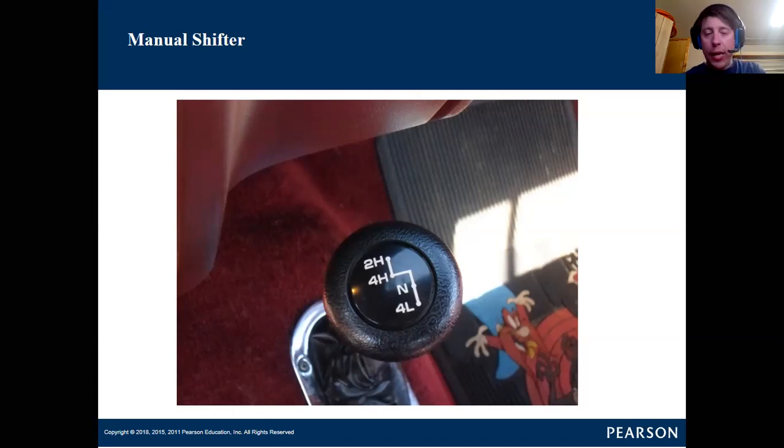Now, that's not always the case. You have to know exactly what you have for a transfer case. There are arguments on the internet, internet warriors that swear up and down their vehicle can be flat towed, and then you go look it up in service information, and sure enough, it can't be, even though it has a neutral feature, because it has to have the input to spin. The input shaft on it has to spin in order to spin the hydraulic pump.